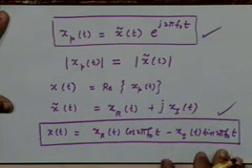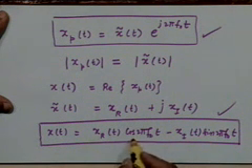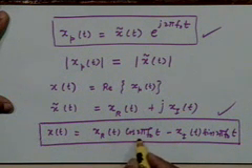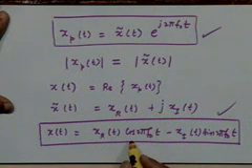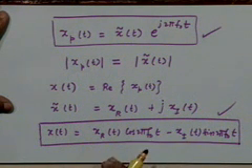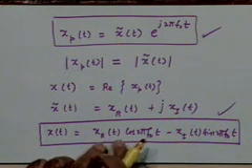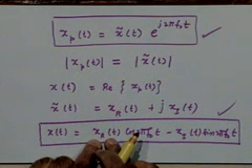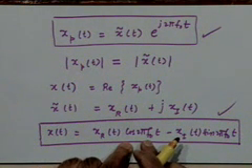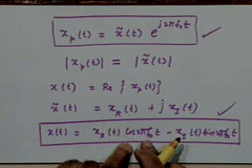The bandpass nature of the signal comes from the fact that there is a sinusoid present at frequency f naught. What is important is that it is a product of a low pass term and a single frequency term, or a band pass term.